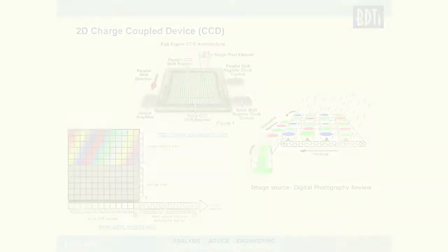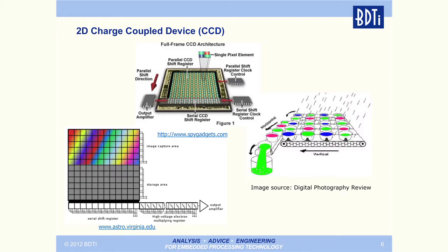If you've heard of a rolling shutter versus a global shutter, the issue becomes that when you move a camera really fast, the image tends to sway like this. The CCD you can actually run as a frame-transfer CCD. You don't get any image movement, any image distortion when you move. And that's because of that storage area. That does require, though, that the CCD be twice as big. It's basically 2 sensors, so it's twice as big as your overall resolution needs to be.